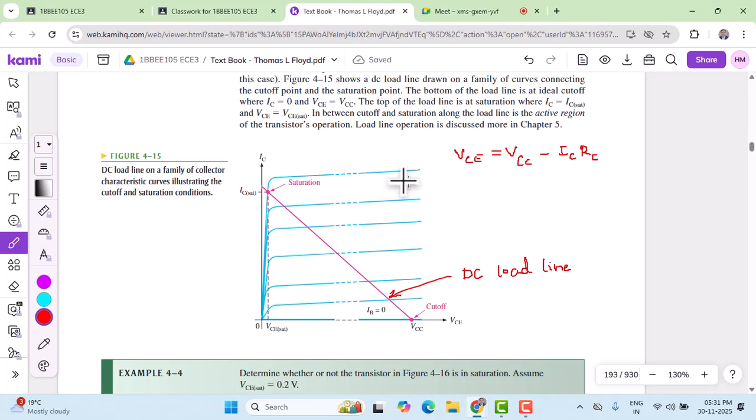Now, as temperature keeps decreasing, the beta DC also decreases, and as the temperature keeps increasing, beta DC also starts increasing. The y-axis here shows the value of beta DC, and the x-axis is going to be the collector current. So we have shown how beta DC varies with temperature and with collector current.